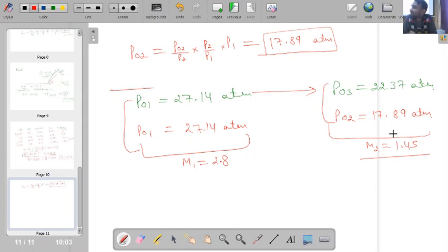Is this point clear? So it means that in any situation, if we want to decrease the Mach number without much loss in the pressure, then our better, efficient option is to use the combination of incident and reflected shock waves.